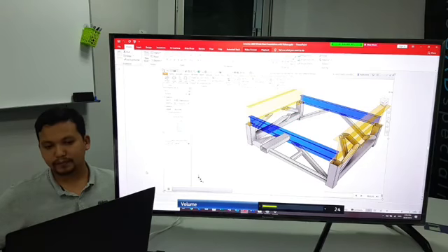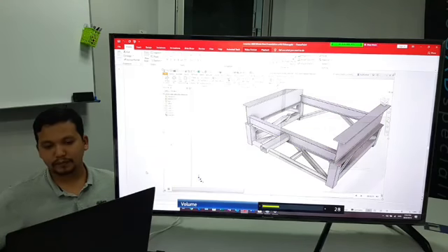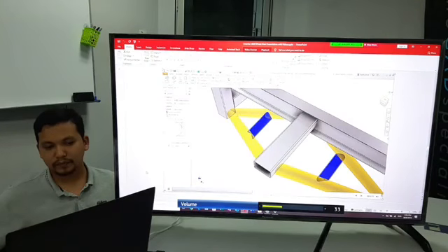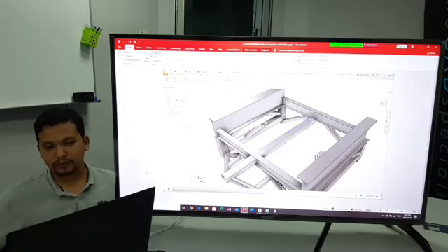No need to select additional options to operate on multiple members at the same time. The notch command has improved options for creating custom profiles. And when notching tubes, the notch with perpendicular cut option helps you create a profile ready for laser cutting. The lengthen and shorten commands now allow you to specify asymmetrical offset values. And the trim command allows you to select which side of the member to remove.